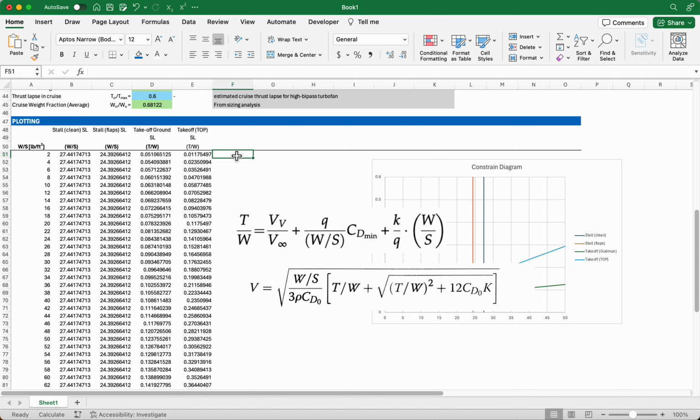So what I'm going to do now for our best rate of climb is plot 3 columns. The first column is going to be our best climb speed, and the next column is going to be our dynamic pressure Q based on our best climb speed, and then our third column is going to be our thrust to weight ratio based on this top equation here. So I'll leave these equations here for us to reference.